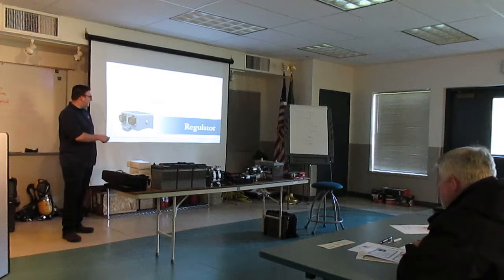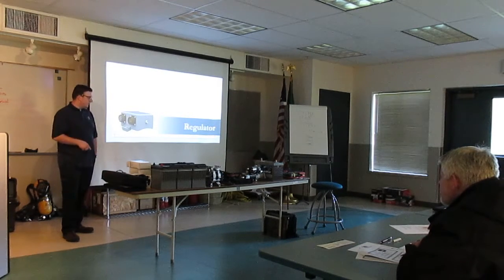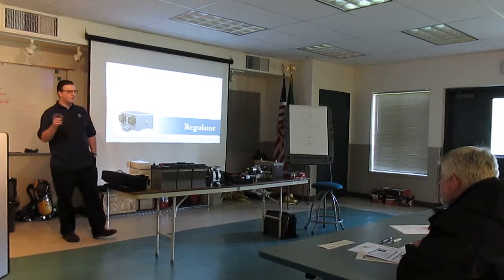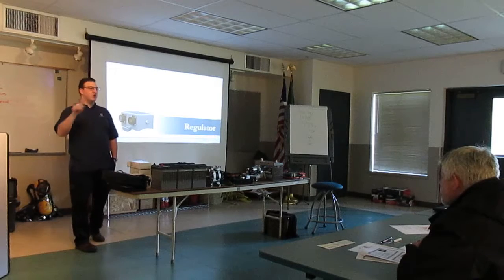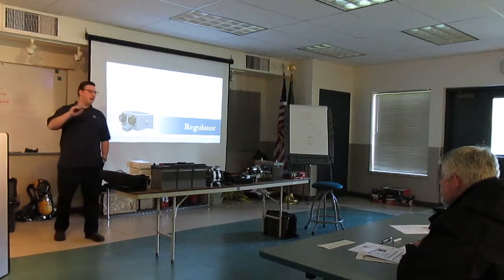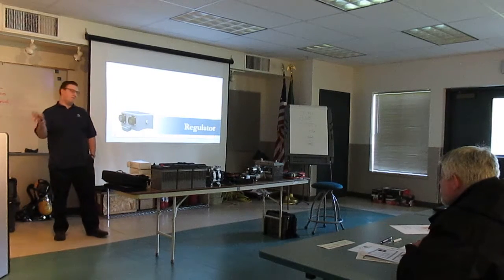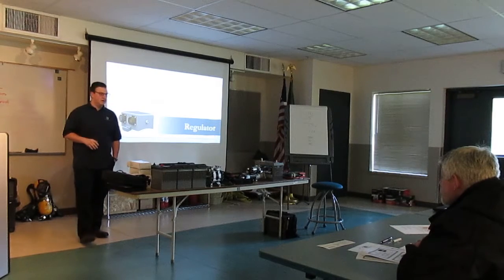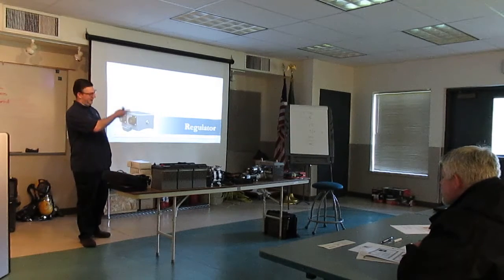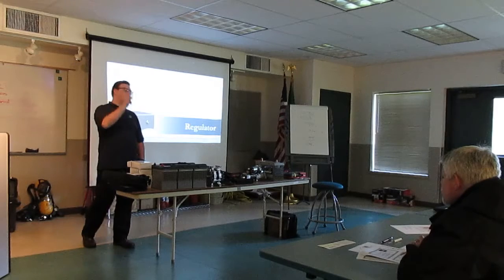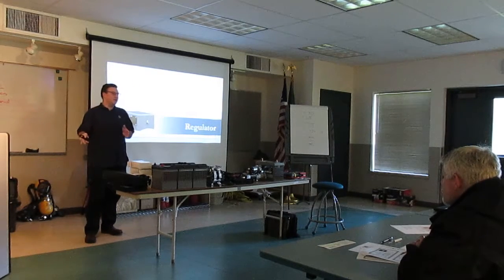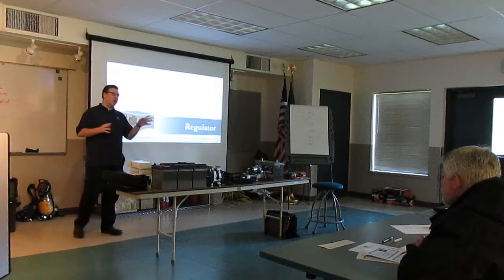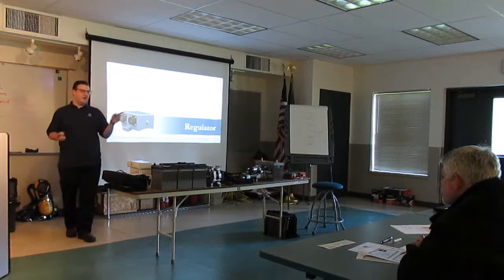And you can also have multiple alternator systems. So in some cases where they have 2 alternators, we actually have it where our regulators will talk to each other to figure out who's doing more of what loads. We prevent leader-follower, but let them run more in parallel. So not so much one guy taking the brunt of it and the other guy just hanging out. They'll actually share those loads throughout the system and they're not fighting each other.